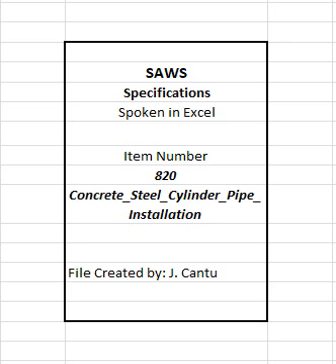Provide lay schedule of pictorial nature indicating alignment and grade, laying dimensions, welding procedures, fabrication, fitting, flange, and special details, with plan view of each pipe segment sketched, detailing pipe invert elevations, horizontal bends, welded joints, and other critical features. 4. Indicate station numbers for pipe and fittings corresponding to drawings.